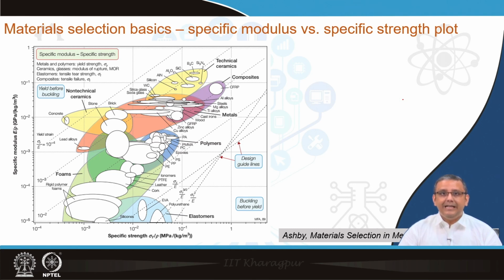And there you see that composite materials, with their most optimum combination of both Young's modulus and strength at a low density, are the best materials for these applications. Metals, although having good strength, because of their high density actually perform poorer than both ceramics and composite materials. And there are actually many such material property charts.